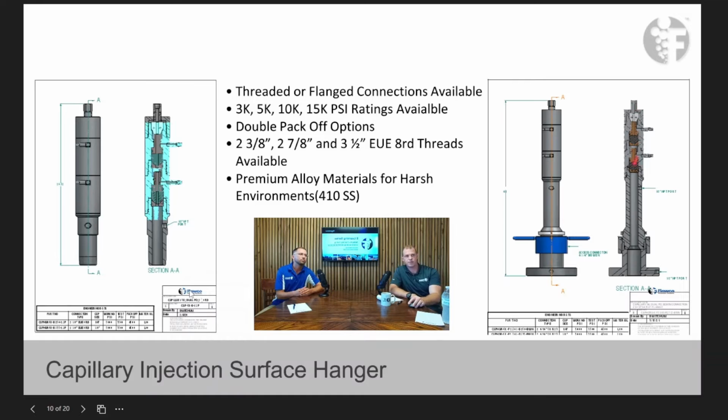And then the cap tubing is deployed down the center of this through the wellhead. That's right. Okay. So I've got a question for you on this. If you're running the cap tubing down through your wellhead and across your master valves, what happens if somebody shuts a master valve? I was hoping you would say that. I get that question a lot. That does happen, no matter how many signs you put on or chains you put on. Sometimes some guys will close it, and then next thing you know, you lose your string. So the master valve will cut the cap tubing? Yes, it will.